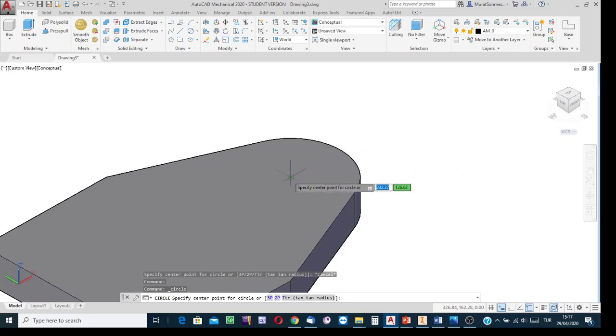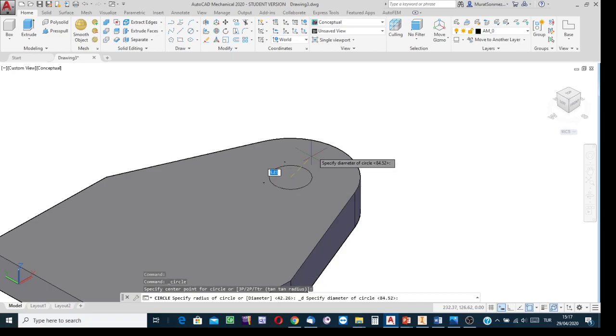Thanks to snap being enabled, the center point of that arc will be highlighted, and bringing the cursor to its vicinity, you can indicate it as the center. Since I deleted the valuable part of the circle to have one region only, here I need to create that circle again.